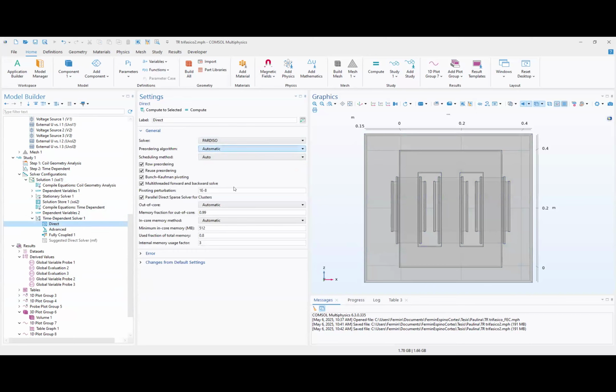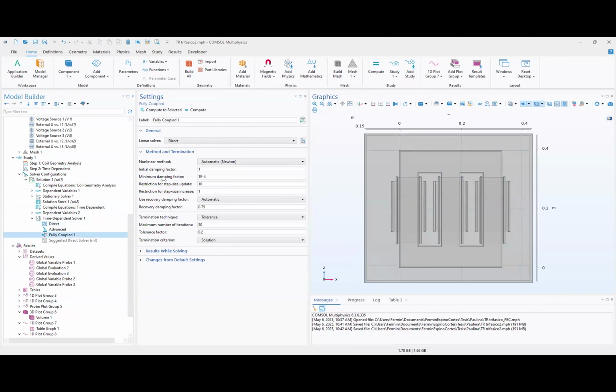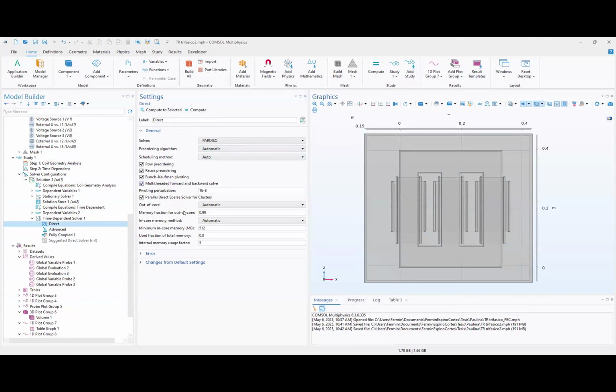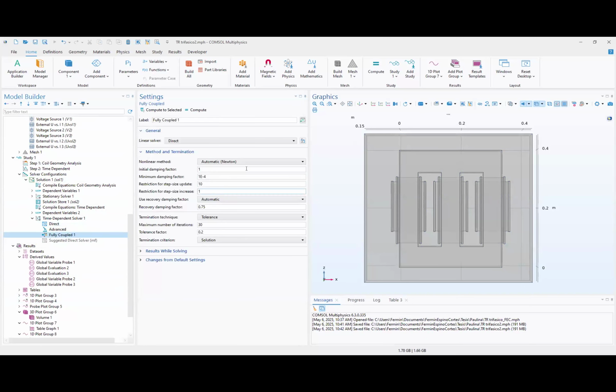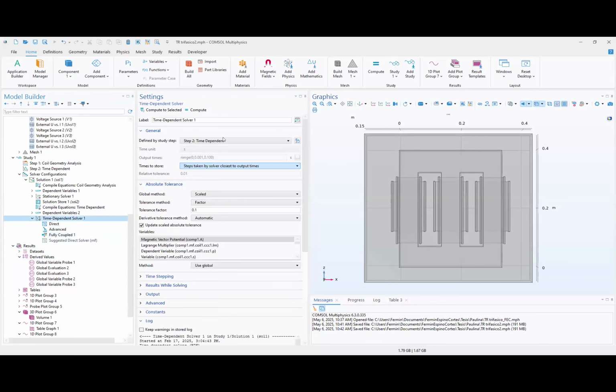The second recommendation was to use Pardiso in the time solver, as you mentioned, and also in the fully coupled solver. Let me show you where. Automatic. Well, there is another part where we have to change something. I can share the time-dependent solver. Where you mentioned the Jacobian update every iteration, they also recommend that, and it works very well.